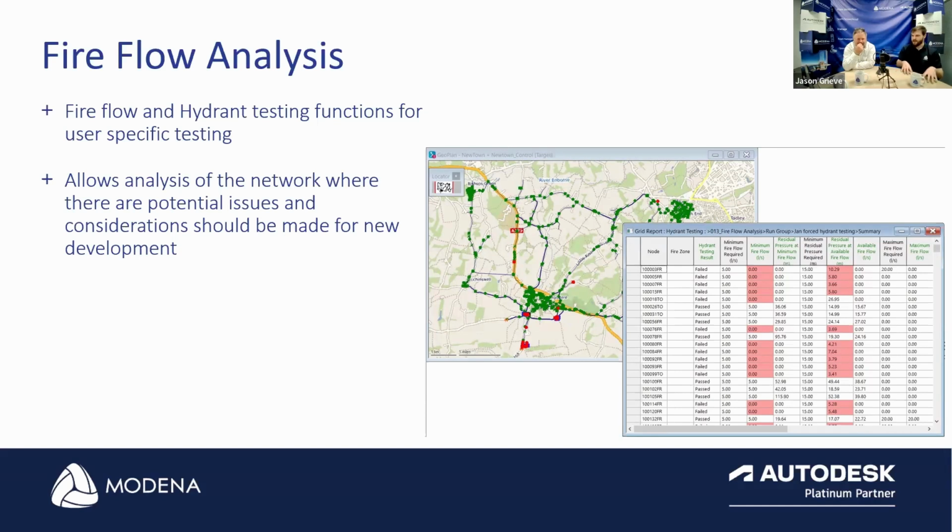And then we started running multi-flow analyses where we actually started picking key locations where we thought our pipe network was too small to actually get that flow pressure through it. So we actually had multiple hydrants firing at the same time. And this gave us a better global understanding of our network. Is maybe one of our feed lines from a reservoir, the bulk line, too small? Should we have a situation where, even though they might be three districts away from one another, that still has an effect on the network if both of those hydrants are firing at the same time?